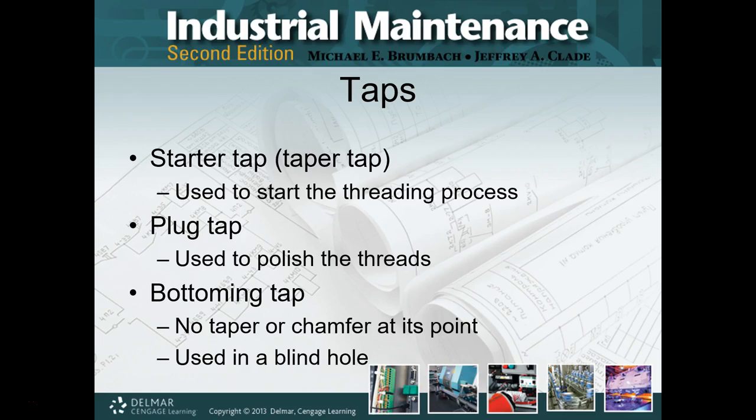Plug tap, I bounce back and forth. I still like plug taps. It's not as severe as a taper, but with practice, you can use a plug tap to start a hole, get it threaded, and away you go.